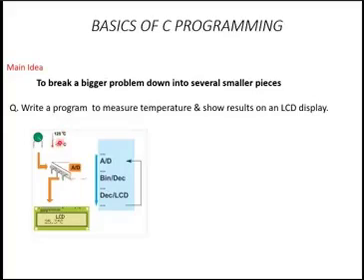We want to measure sensor temperature, to be precise, temperature, which is an analog signal, and then using a microcontroller, read that temperature value, and then display it on LCD continuously. Any changes will be updated through the LCD. So the first thing, as you can see through this diagram, in order to measure temperature, we need to use a temperature sensor.